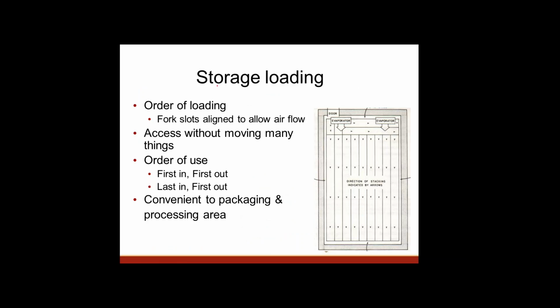Storage loading, you know, I kind of alluded to this previously. One, if we've got fork slots, we want them all the same way, so we get basically airflow down and then through the product and back to get good airflow.